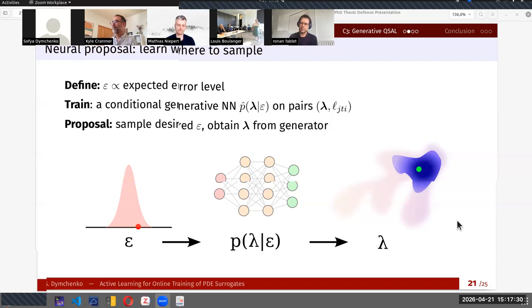So its size and how fast it trains would depend on the discretization. In this case, you have just the parameter lambda, which doesn't depend on the discretization resolution. If I train the surrogate for 256 and then go to 1000 by 1000, the neural network size stays the same, which makes it scalable.